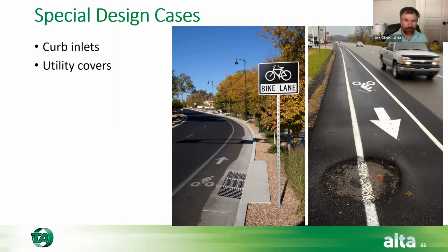These devices typically have a different coefficient of friction than the rest of the pavement surface. And so if you've got a downhill or a braking zone, and these are in the bike lane, you could have people lose control of their bikes when their wheels change and they're suddenly not slowing down anymore or lock up because of going over a wet manhole lid or something, for example. So those are things to be thinking about.